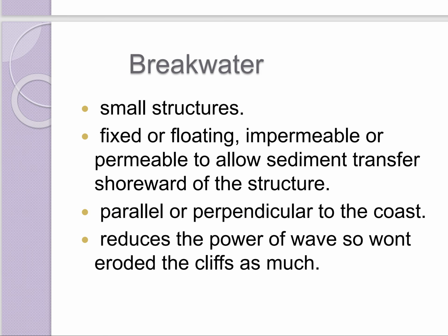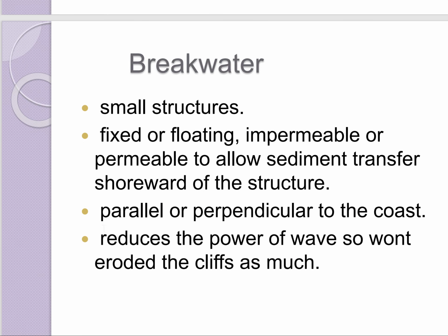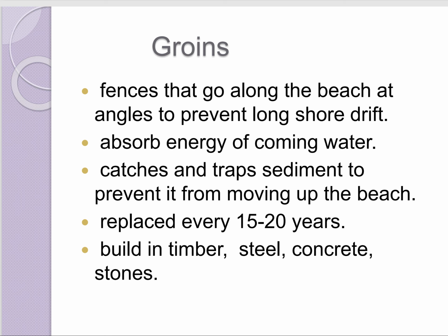So next one is breakwater. Breakwater is a small structure, fixed or floating, impermeable or permeable, to allow sediment transfer shoreward of the structure. So this is a structure called breakwater, which may be fixed or floating. These structures allow the transport of sediments to the shores. So these structures are either parallel or perpendicular to the coast, and it reduces the power of waves, thus reducing the erosion.